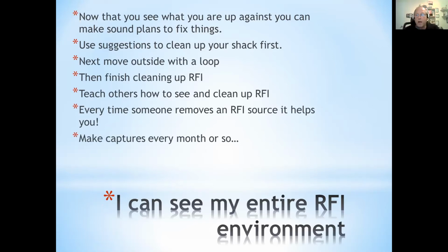Make captures about every month or so, right? Get your SDR, hook it up to your computer, and take a snapshot of what your RFI environment looks like, and see if there's anything new in there, right? Maybe your next door neighbor got a new hair dryer that's an Internet of Things hair dryer, and sure enough, it's putting out RFI. And every time they curl their hair in the morning, it knocks you off 80 meters. Well, you can make a capture of that.